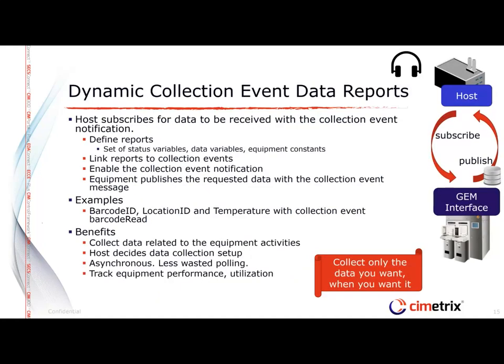And there's another feature related to the collection events that I mentioned. And this is a data collection. It's called Dynamic Collection Event Data Reports. What this means is that for every collection event that an equipment publishes, the factory can ask the equipment to send data with that event. And again, this is done by subscription. So the equipment will publish and document the available data, but then the host will choose the data they want